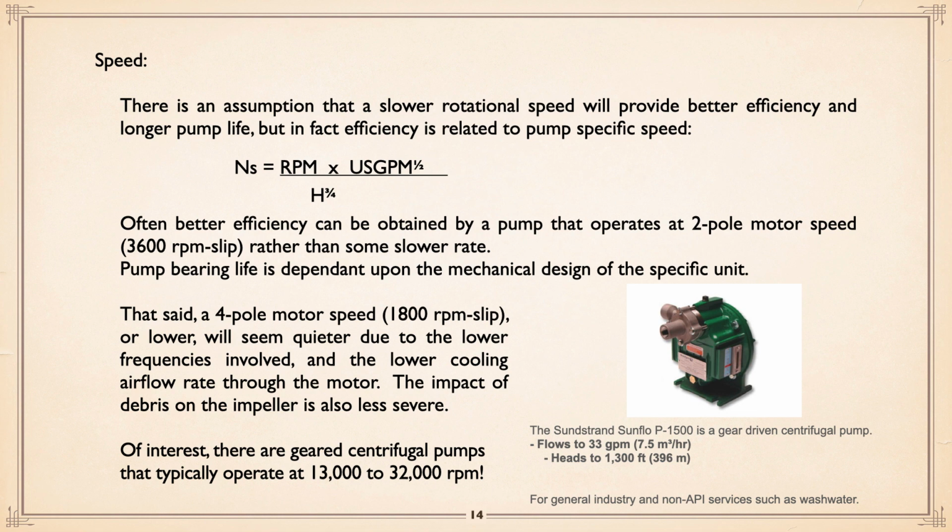Pump bearing life is dependent upon the mechanical design of the specific unit. Of interest, you tend to think that a 4-pole motor speed or lower, in other words 1,800 RPM, will seem quieter due to the lower frequencies involved and the fact that the cooling flow through the motor is less. And the impact, if a big rock gets in there, obviously is going to be less if it hits the impeller.